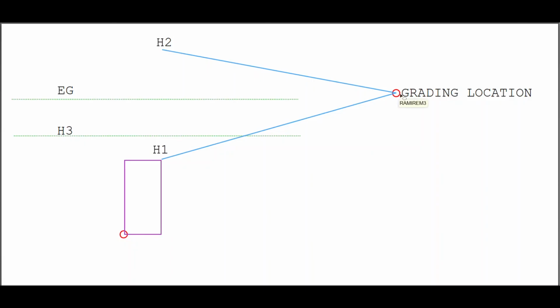This might represent an adjacent roadway that grades back towards our wall. The third step will be determining the minimum and maximum grades. In our situation, we were given a limit of 2 to 1, and so that's what I have here. 2 to 1 back, and then 2 to 1 going up, which this is the ideal point, but anything between this would technically be feasible.